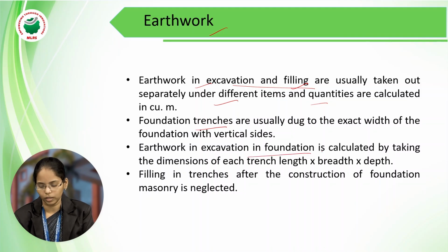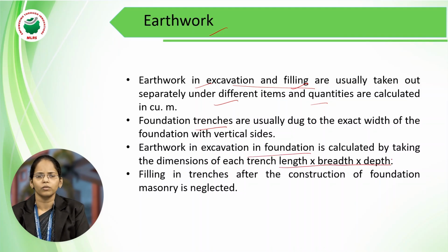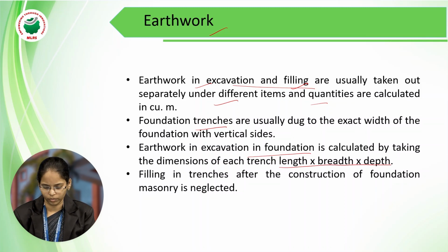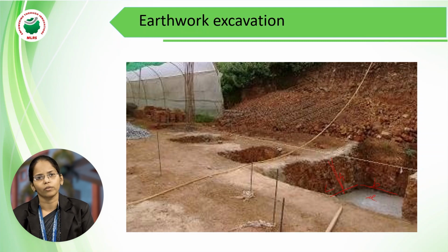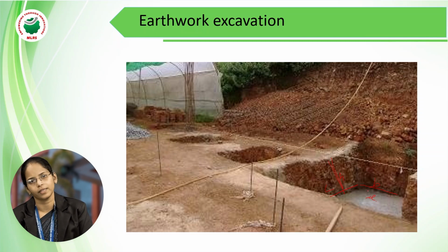So earthwork in excavation for a foundation is calculated by length into breadth into depth. So L into B into H. This is how we calculate for a foundation. If we see this figure, here we need to lay a foundation. So PCC, this is a PCC bed, and we need to lay a mat there, and next RCC mat, and then foundation concrete, and then footings. Here this we call height, this is length, this is breadth. So some parameters. L into B into H gives the volume of the foundation or excavation or trench.